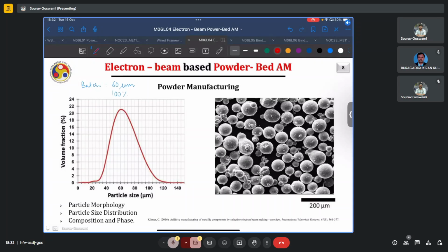This is simply physically impossible, or even if possible, the costs will simply be too high to justify this. What you always have is a distribution of the powder particles. Now, this distribution can be controlled. So, rather than having such a wide distribution, this can be even tighter. And with such increased quality control, the costs will also shoot up.